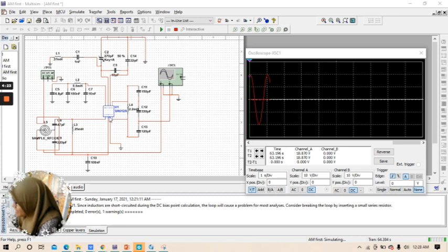The mixer outputs at pins 4 and 5 are also internally biased. Each output is connected to the internal positive supply by a 1.5 kilo ohm resistor. This permits direct output termination, yet allows for balanced output as well. The oscillator pins are connected at pins 7 and 6.